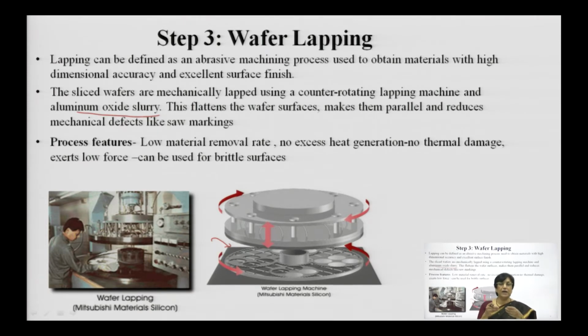In Hindi, we call it lipna, like you apply something to a surface to soften it. So, similarly here also we are doing the same process, we are trying to immerse the wafers. Now, this process has specific features. In this process you do not have much loss of silicon as a whole. Secondly, there is no excess heat generation, so there is no damage because of heating. Thirdly, you do not have large force being applied, it is done slowly. This is just abrasive rolling, done to prevent any additional damage.